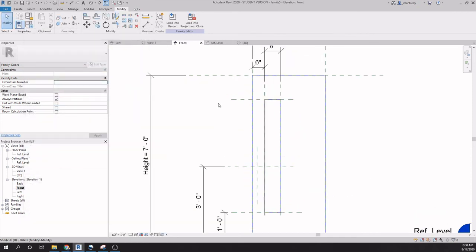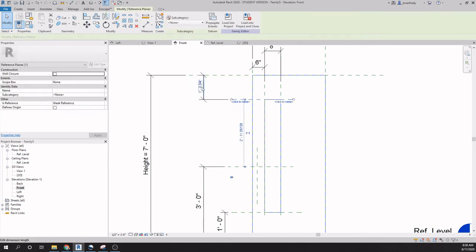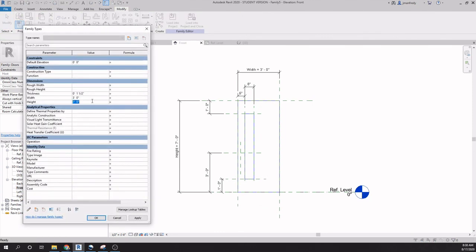I need one more dimension from here to here. And it'll be locked, in my example, as a foot. So I'll take that measurement and lock it. So lo and behold, if I come back here and make the door 8 feet, you'll see that that foot follows. So that's working, that's functioning properly.